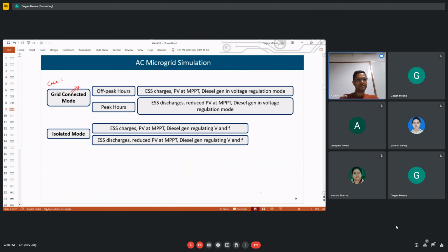Here we can see, right? Yes, sir, shunt will be used for voltage. This is the series active filter, which is the dynamic voltage restorer. So series we are using for voltage related problems, and shunt we are using for current related problems. Here it is drawing current. So series is used for voltage, shunt is used for current related problems.